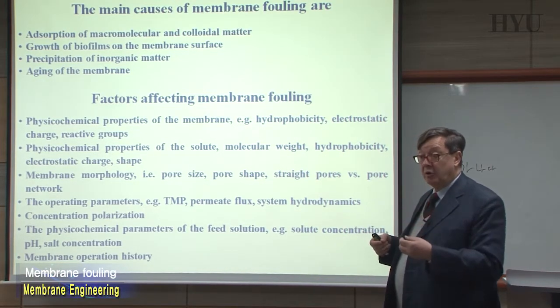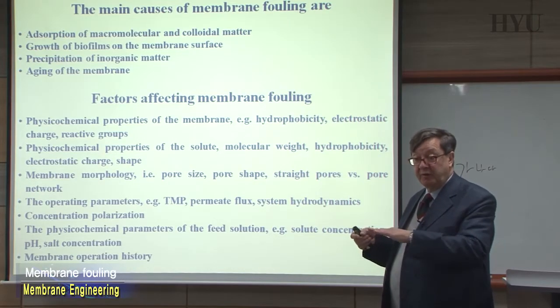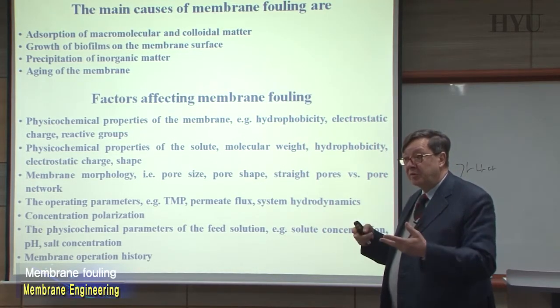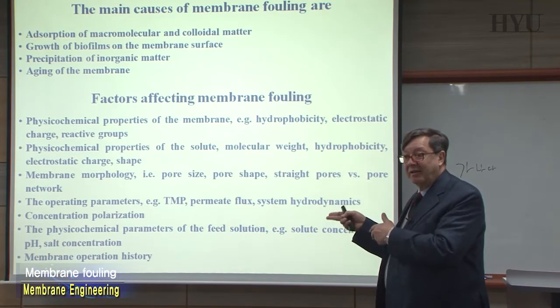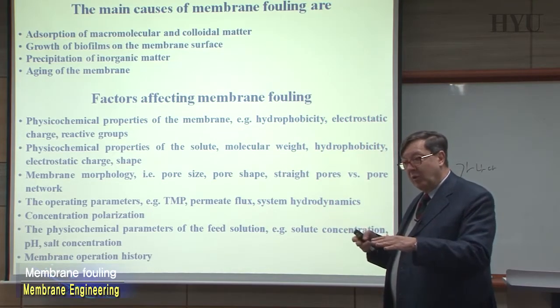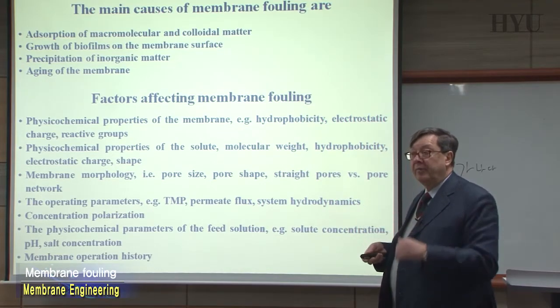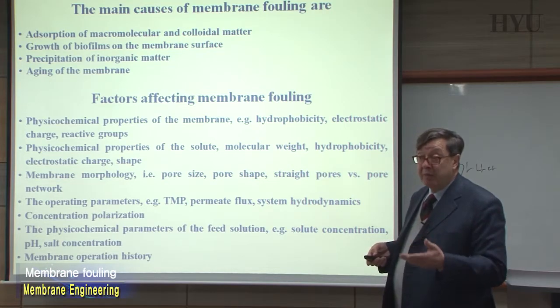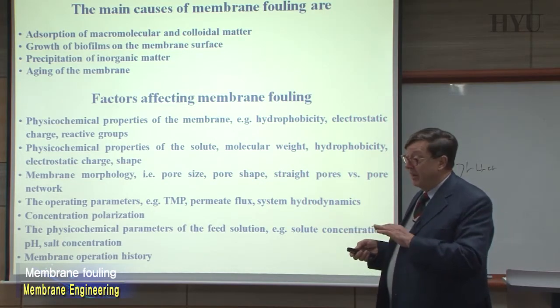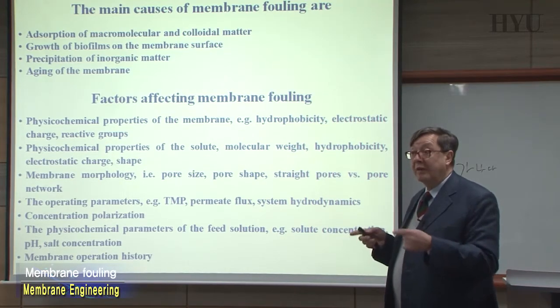This means these microorganisms that form initially the film, they start to produce mucopolysaccharides, some chemicals, and these are the ones that can penetrate in the microporous structure of the membranes, the nanopores of your membranes, and are very difficult to be removed when they are already there.